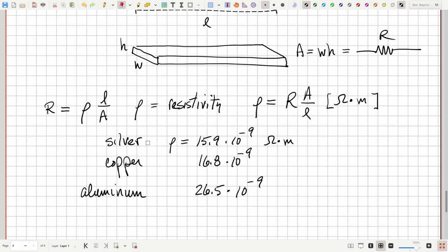So obviously we don't use silver for a lot of wiring because it's so expensive, so rare. Although it is used for some very high precision circuitry where the cost is not as much of an issue as the lower resistance. Copper is quite a bit cheaper than silver and has only slightly more resistance. So it by far dominates wiring for circuitry and household uses at smaller scale. Aluminum has considerably more resistance, not quite a factor of 2, but it's much cheaper and lighter than copper.